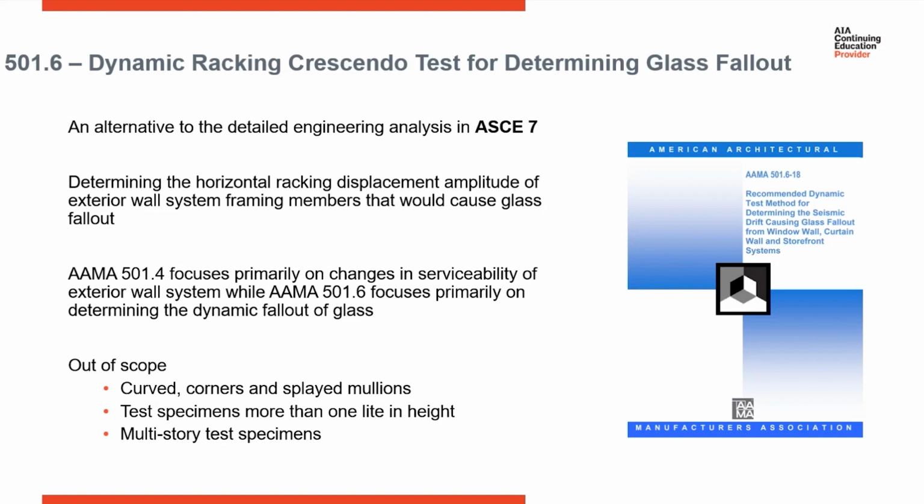Again, while AAMA 501.4 deals with serviceability, you're doing air and water testing. AAMA 501.6 is a standalone test that just deals with determining the glass cracking and the glass fallout. The scope of this test will be curves, corners, blade mullions, and multi-story test specimens.